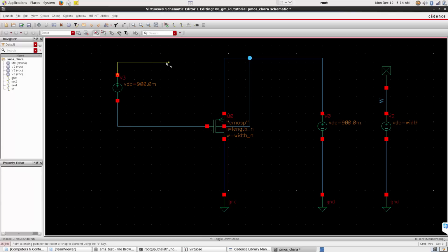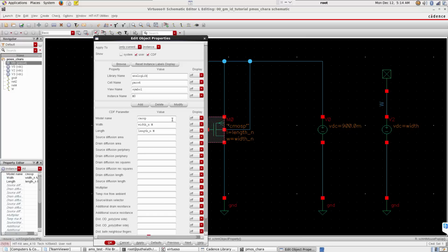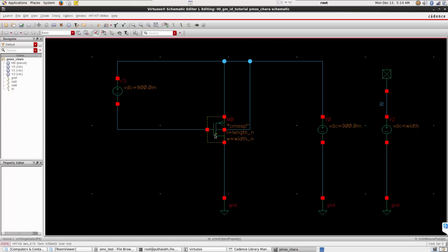So if we want to use our previous state and all the previous expressions, we should not change the name of any parameter, because earlier we had a MOSFET named M0. So here also we are using the same M0. But if we are using some different name, suppose M1 here, then again you have to open the save op.scs file that we did here.